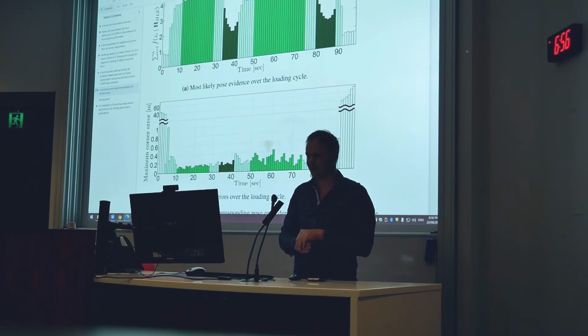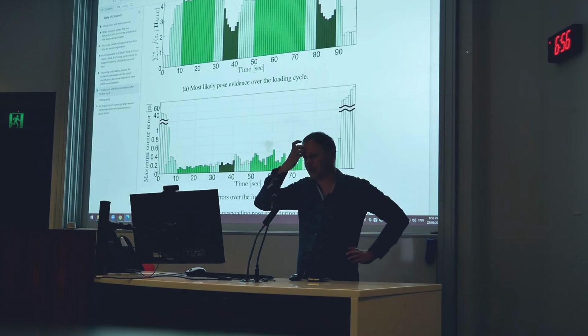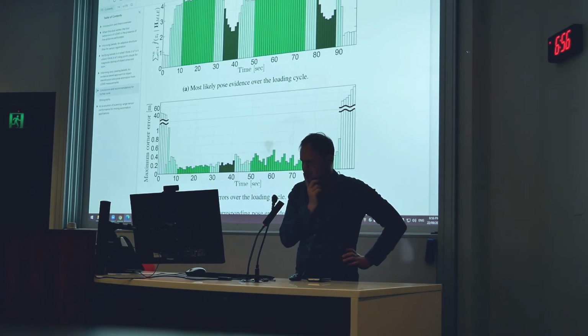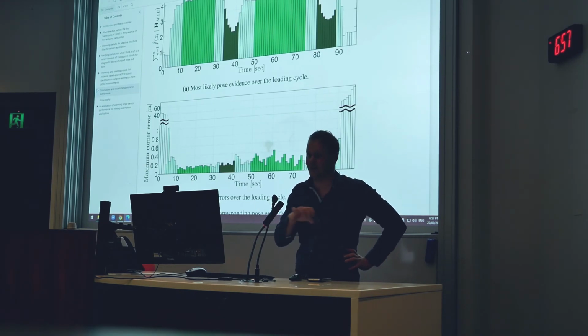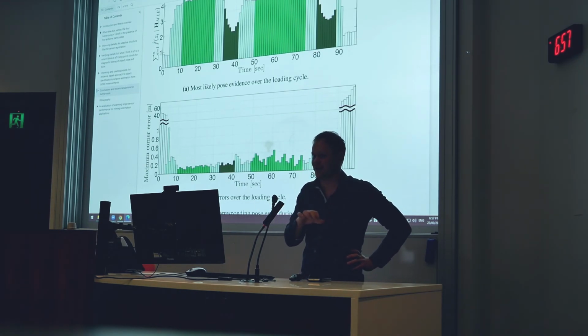That got us down to maybe a second or two for a 6 degree of freedom pose estimate, the one that you saw. You saw that got it pretty quick. But you can subsample the data to make it faster. You can have fewer hypotheses to make it faster. It seems to be linear with the number of measurements and number of hypotheses. So if you subsample them and have a smarter searching heuristic that doesn't need as much data or as many hypotheses, you get there faster.